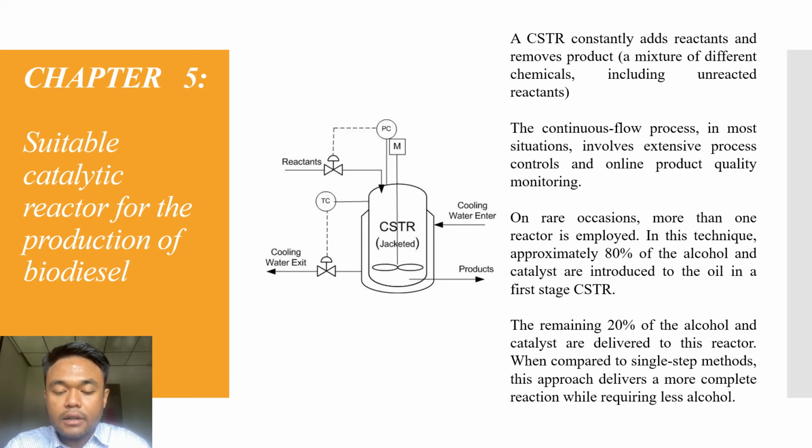For this technique, approximately 80% of the alcohol and catalyst are introduced to the oil in a first stage CSTR. Before entering a second CSTR, the reacted stream is treated to a glycerol removal process. The remaining 20% of the alcohol and catalyst are delivered to this reactor. When compared to a single-step method, this approach delivers a more complete reaction while requiring less alcohol.